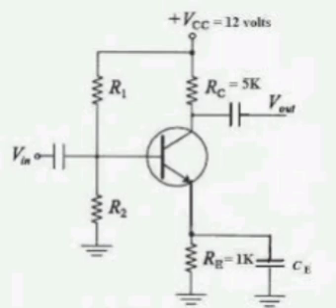Third B question. A 10 kVA, 2500/250 volts, single phase transformer has the following parameters: primary winding (HV side) resistance R1 equal to 2.4 ohms, leakage reactance X1 equal to 6.00 ohms; secondary winding (LV side) resistance R2 equal to 0.03 ohms, leakage reactance X2 equal to 0.07 ohms.